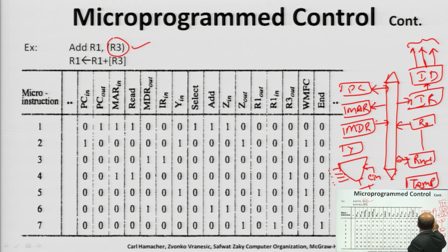This was a simple architecture that we need to remember always. Now, you can see to execute this particular instruction, various components are utilized, and to control these components, different control signals are issued. When a particular control signal is to be issued depends on what type of program control we are using, either hardwired or microprogram control. If we are using microprogram control, in this case the 7-step program can be written like this, the program to execute this instruction.